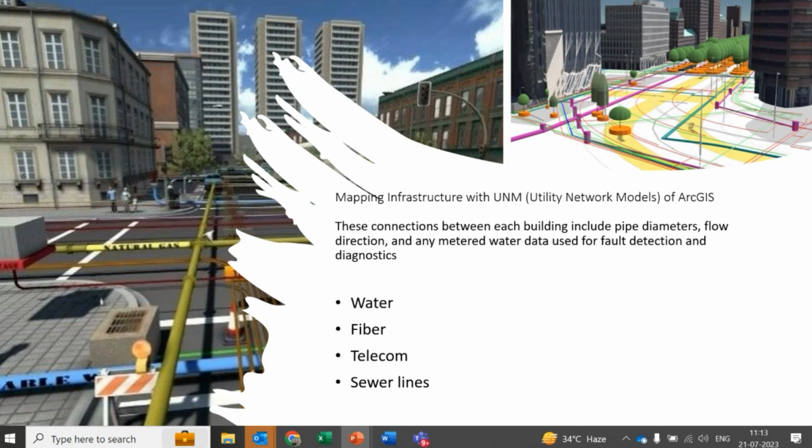Suppose an individual household is asking for a network connection from the house to the main distribution line. The complete set will come with a gate valve, with a scour valve inside it, the complete connected network will come. Inside the pumping station, it will come with all the different sorts of valves, all the equipment that is required for a pumping station, for a WTP, for a STP.